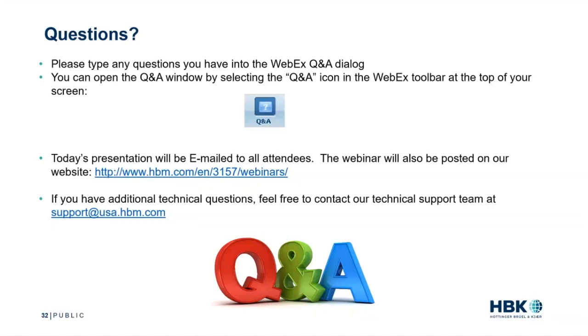Yes, it has. So in individual motor testing, let's say you're mounting a motor to a direct drive test stand, measuring WLTP becomes difficult because there's a lot of dynamic power measurements made. And if you're not using something capable of making dynamic power measurements, your measurements are not going to be very good. And WLTP has some pretty fast transients in it in regards to power analyzers. So HBM offers some solutions that measure dynamic power very well, so we can help with that.